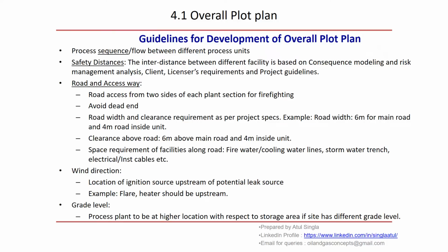Wind direction, location of ignition source, upstream of potential leak source. Okay. We need to locate all these unit blocks and process units based on wind direction. The fire should not transfer from one point to another. For example, the flare header should be upstream.